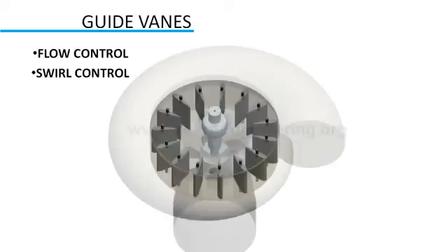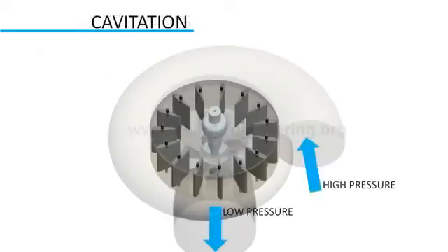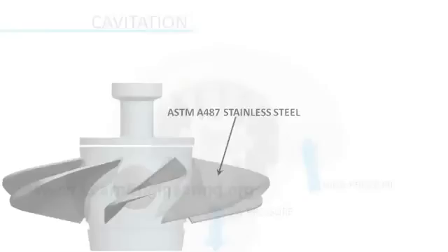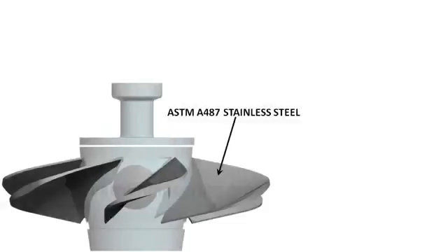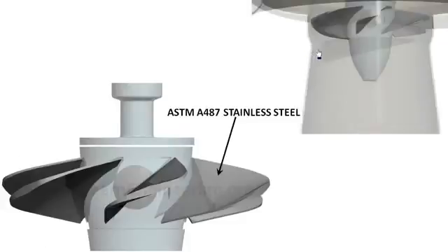The biggest challenge in the design of a Kaplan turbine is how to overcome the problem of cavitation, which causes material erosion and vibration. Cavitation is unavoidable in a Kaplan turbine, since in most regions pressure goes very low. But damage due to cavitation can be reduced by using suitable blade material and anti-cavitation fins. The draft tube, which transforms dynamic pressure to static pressure due to its increasing area, also helps in reducing the cavitation effect.